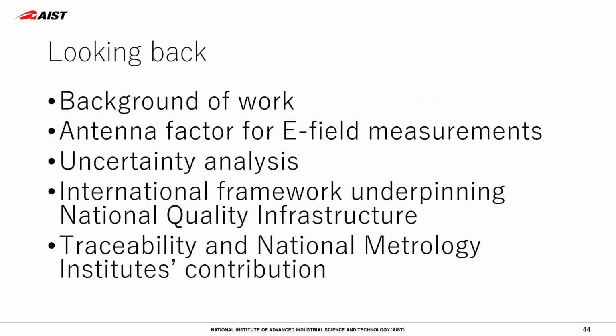In this tutorial, we went through E-field metrology. Firstly, the definition of the antenna factor to accurately measure the E-field strength and the conditions required to realize the definition were considered. Then, three methods to obtain the antenna factor were introduced, followed by the uncertainty analysis to discuss the reliability of the measured results. Also, I touched upon the traceability of the national standard and how the National Metrology Institute claims their calibration and measurement capability is equivalent to other institutes. Hope you can feel a flavor of metrology, even a bit.